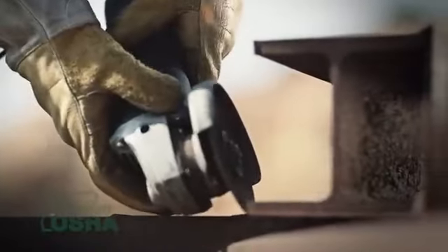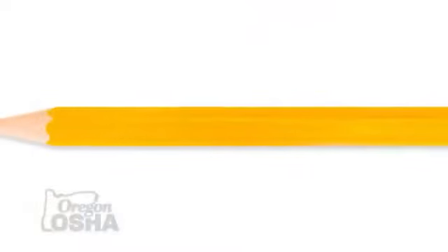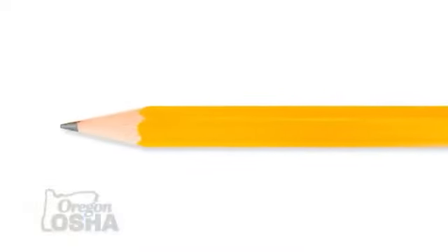We have leading edge, and we also have leading edges that incorporate sharp edge hazards into them. A good rule of thumb when we're looking at something that could be a sharp edge, whether it's a sharp steel edge or a sharp concrete edge, is anything with a radius on that edge that's less than a number 2 pencil. We want to start taking extra measures on that leading edge to protect against cut hazards on that lifeline from that sharp edge.